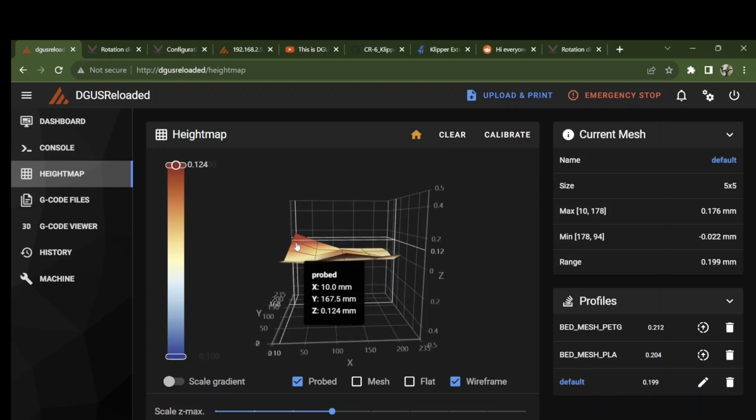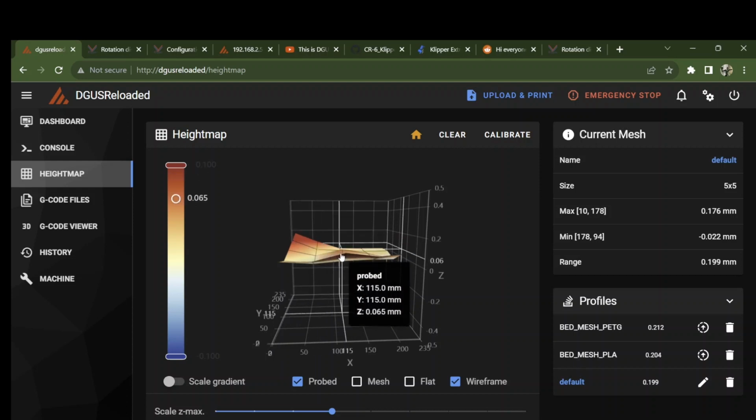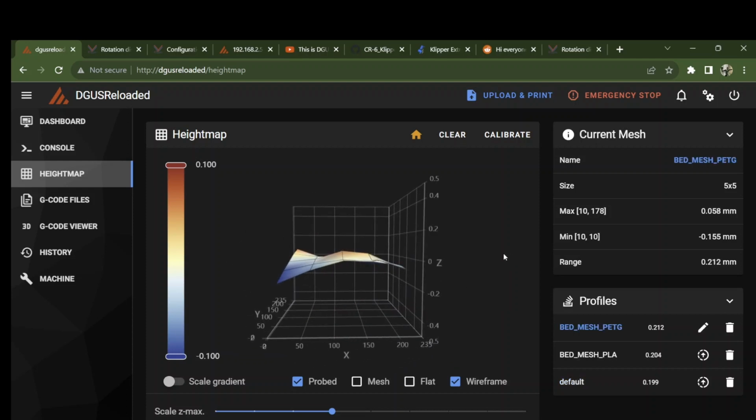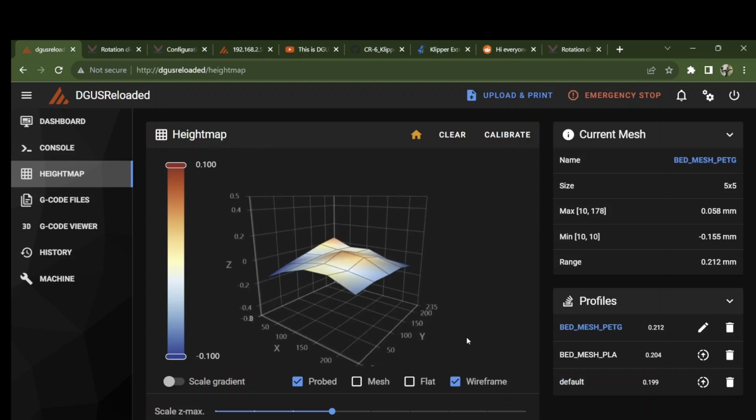Not as depressed at the front, quite high at the back, because it's all relative to the center, and the center is not as pronounced. It hasn't domed up as much when it's cold as it has when it's hot. So there you go. There's my rationale for the 3 different profiles and the mechanism in Printer.cfg for how it's used when printing.